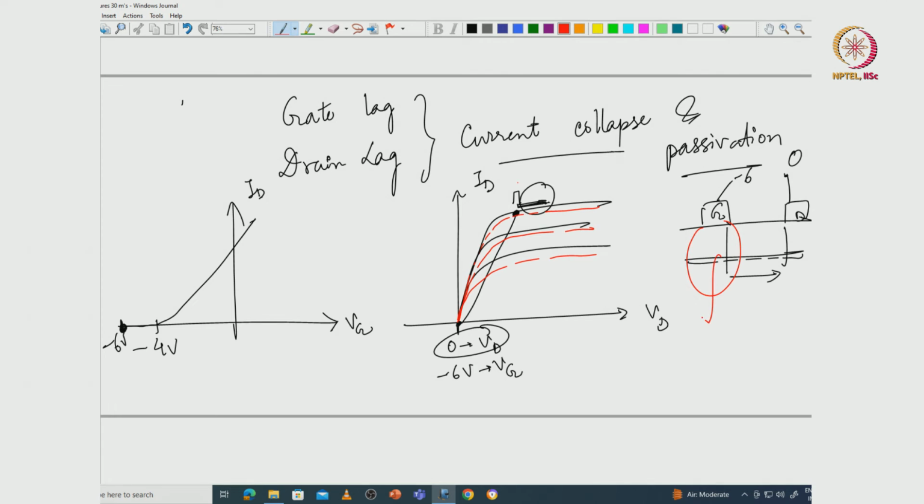Whatever traps or other impurities or imperfections are there in this region, if they capture the electron and are not able to release the electron on time, then you will have this lag. Essentially your gate will go to this pulse, go to off state, and again come back, again off, again come back. Can these traps capture and emit the electrons as fast as these pulses?